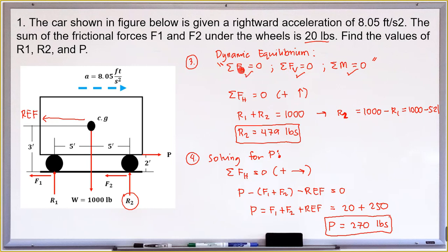But then again, the summation of forces horizontal and vertical is arbitrary because there are some cases that are inclined. So therefore, you can change this axis. It could be at a certain axis that is inclined with respect to horizontal. So it's up to you. Okay? So again, exactly three equilibrium conditions should be followed. So these are summation of forces in two directions, or summation of moment.